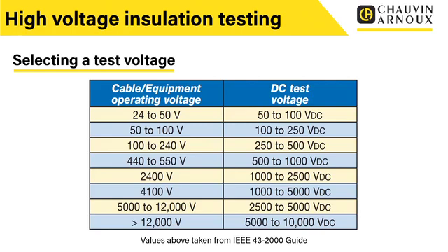But what we don't want to do is put too much stress under it that's actually going to damage it. Remember, we were saying this is a type of non-destructive condition testing. We're not here to try and break this. We're not putting it under stress to break it down. What we're trying to do is use enough voltage to be able to actually determine its condition without causing damage.